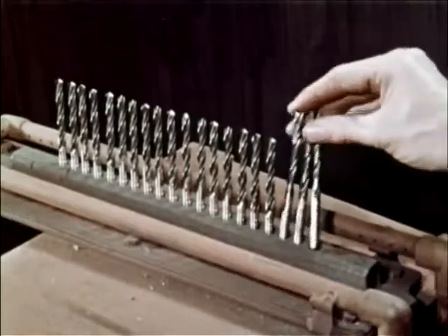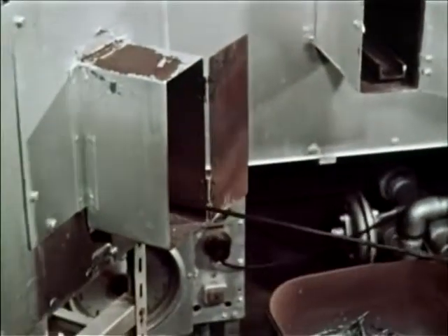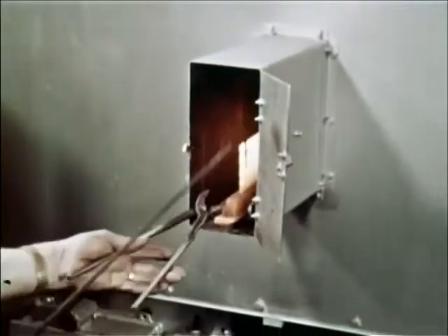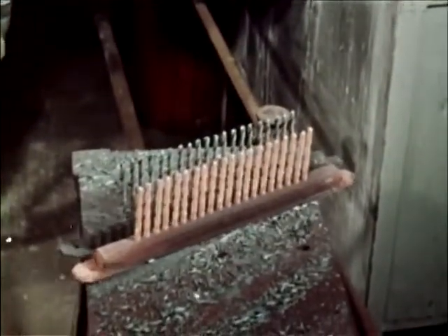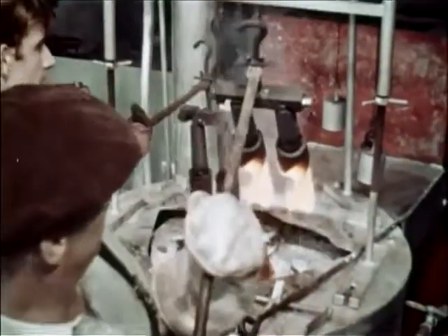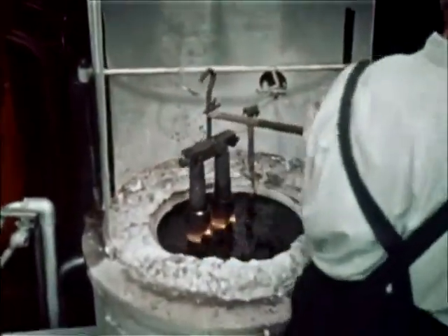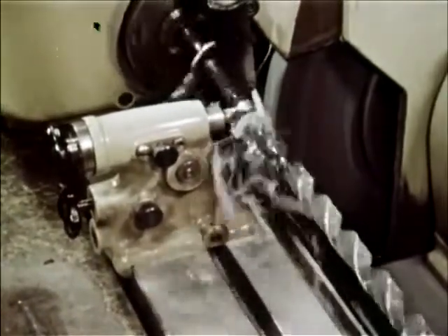Obviously, the drill must be harder than the material it is to cut, yet it must not be so brittle as to chip or break. Heat treatment is therefore a most important factor, and very rigid standards are kept. After heat treatment, the drill is finished ground to close tolerances by cylindrical grinding or centerless grinding in the case of jobber drills.